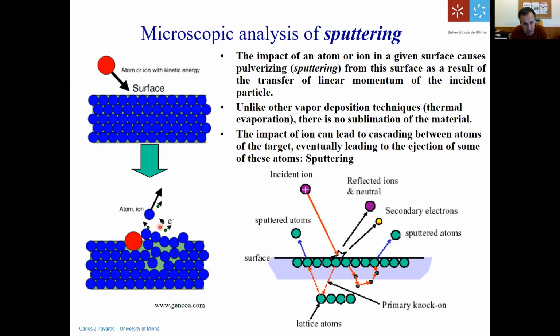And these electrons are very important to continuously ionize the neutral argon atoms which are around the target, and they will become ionized, they'll become red, okay? Like, as I'm saying here, just as a graphic explanation. And then they will hit the surface of the target again continuously, and they will eject more atoms, which will then go forward towards the substrate, okay?